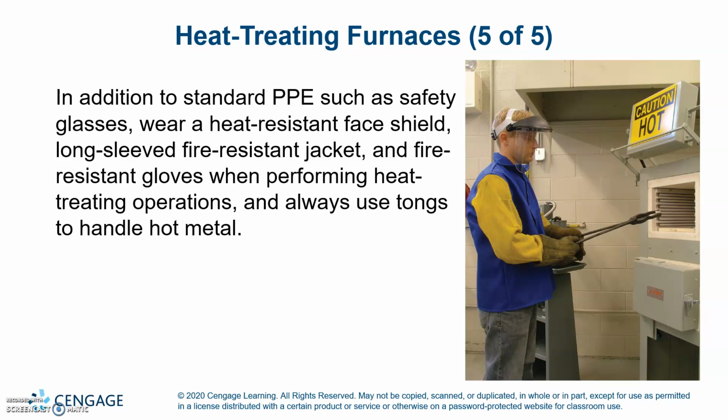In addition to standard PPE such as safety glasses, wear a heat-resistant face shield, long sleeves, a fire-resistant jacket, and fire-resistant gloves when performing heat treatment operations, and always use tongs to handle hot metal.